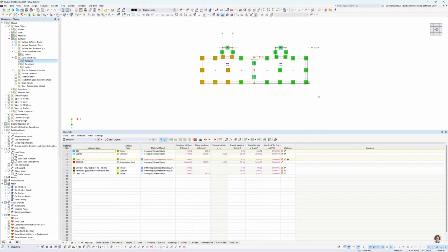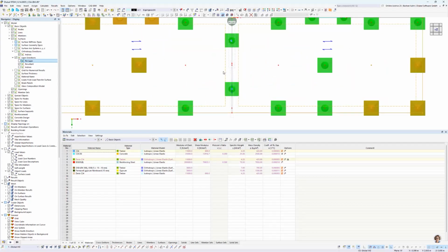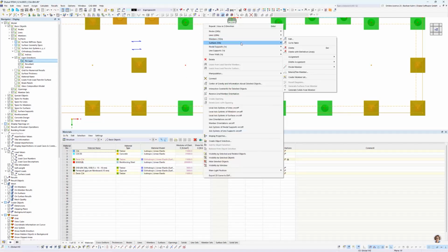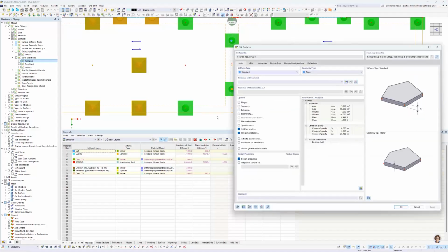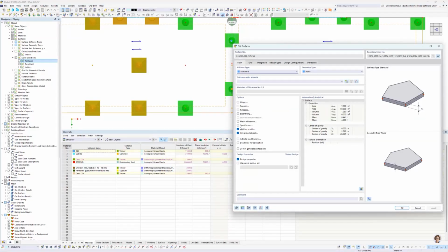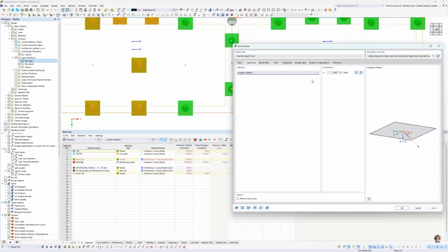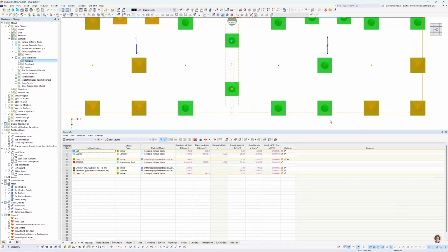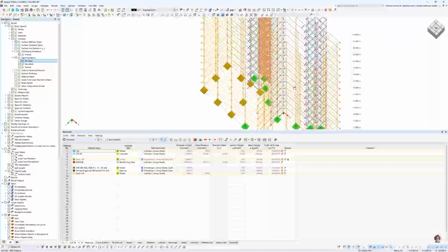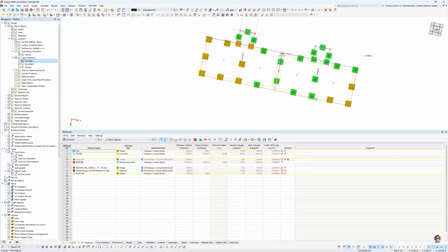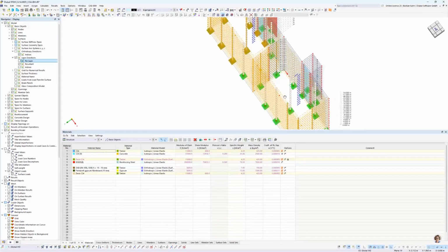Therefore, activate those surfaces, these ones, similar to these ones, and right click and surfaces, edit. And I have here a specific axis that I can orient. So that's rotated by 90 degrees. And I hope now the stiffness orientation is changing. That is changing. So that's perfect.